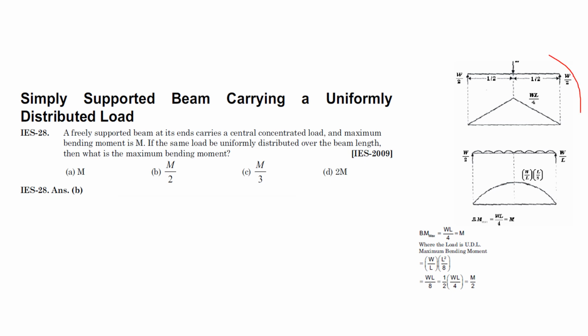So this is the loading condition they are talking about. Here W is acting at the center, and on each side the reaction will be W by 2. This is the shear force diagram, and this is the bending moment diagram.